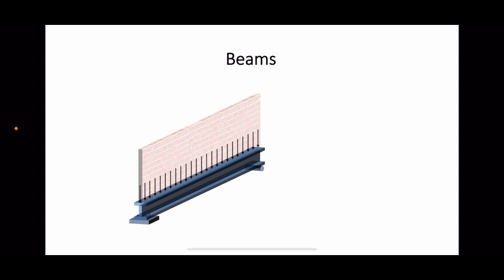In order to design the beam, we need to determine the maximum stress within the beam. For that, first we need to be able to determine the state of stress for any point within the beam. Let's select this point. Please note that when I say the state of stress for the point, I mean the stress on the sides of the cube element. Fortunately, for beams like this one, the state of stress for each point will not be that complicated. Instead, it will look like this.